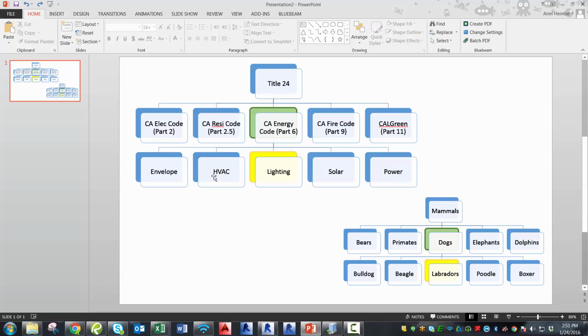So we'll go over power density calcs, how to calculate the fixtures that you have leveraging Revit, and then how to enter them into Energy Pro, and how to print those forms and then fill out all of the extra bits and pieces of the forms in Bluebeam. So that completes the first part of this series. Check out our next video where we'll go over getting totals in Revit and entering them into Energy Pro.